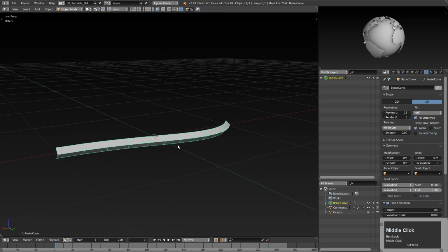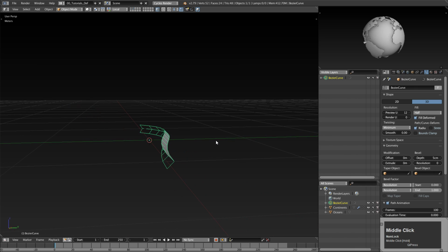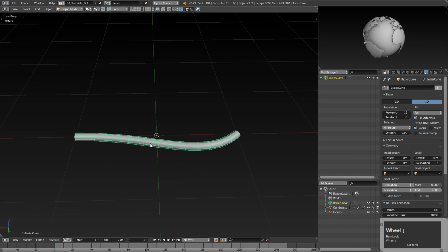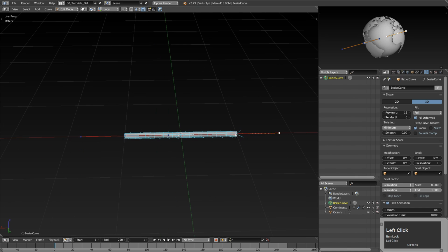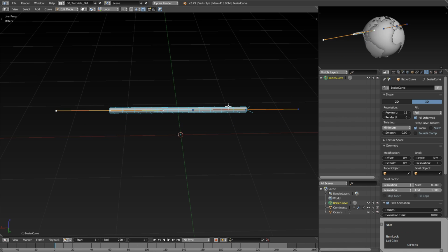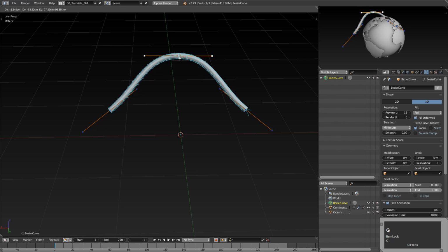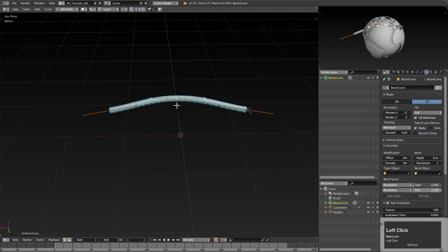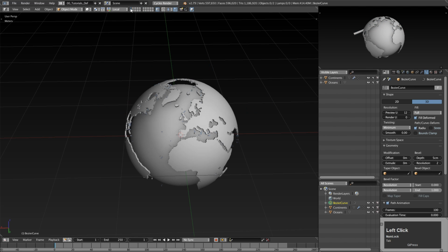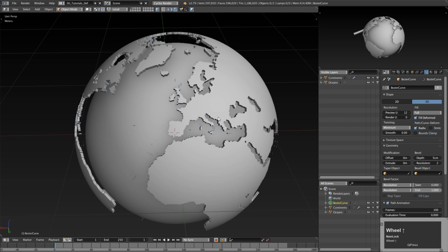As you can see, the geometry doesn't go all the way around, and that's because the fill property is set to half and we need to change it to full. Also, the resolution could be a bit higher. Every arc will consist of just 3 points: the beginning and the end, that will connect some random points on the surface of the arc, and the middle point, which we will use for controlling the height of the arc. We can go back to the first layer and define all the random points that we will need.